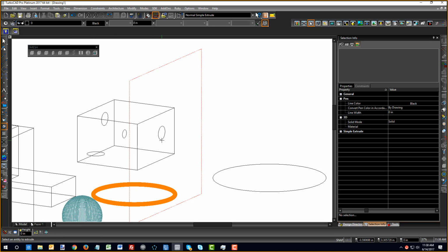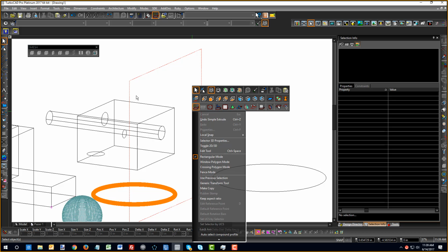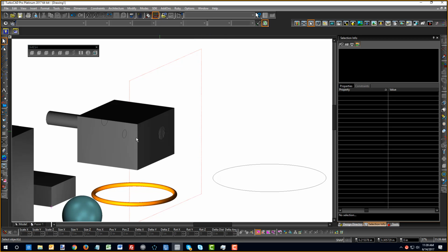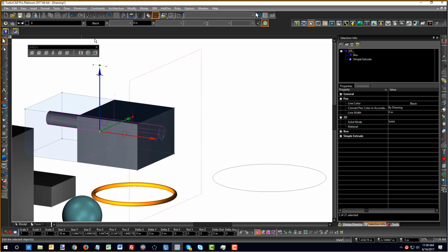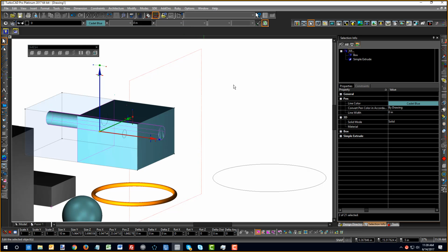I'm going to choose the circle, and now I can either manually draw and extrude this, or I can put in a height by hitting the tab key and typing, and I'll type -10. Okay, and then we get this object here, and let's just change the colors of these so we're looking a little brighter here.